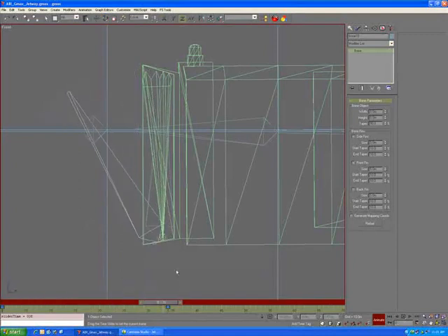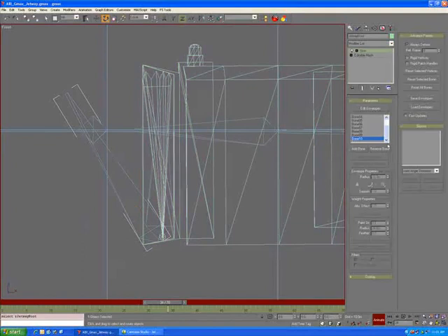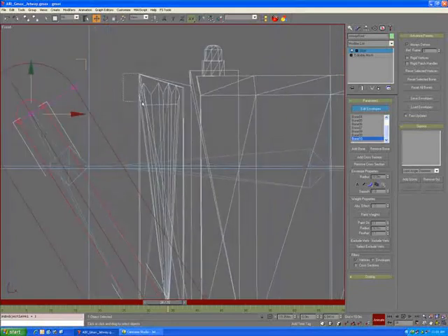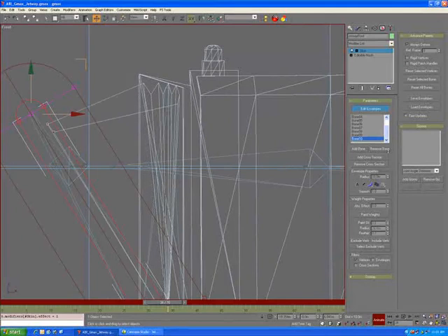So now you can go to that keyframe, go back into your skin, and now you can actually edit the envelopes for that bone. If we select these right here and give them a value of 1, it's going to stretch them way out. So now we can grab these and go, say, 0.85, and you just start to go in, 0.7, and make the Jetway stretch.